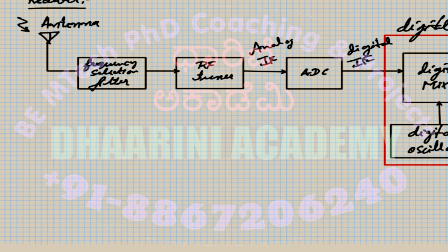If you go for higher or very complicated types of modulation techniques, you may find in the block diagram two more components, for timing adjustment and carrier recovery. If you refer to other books, you may find these two things there, because normally it is non-coherent, so you don't know what frequency you are sending. You need a carrier recovery tool that identifies the carrier frequency. So that part may be extra.